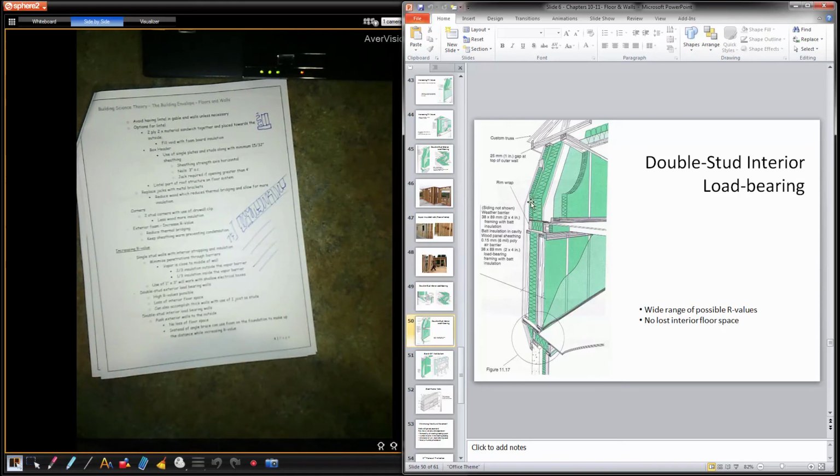But again, just overloading insulation. Insulation in between the sides, insulation in between the walls, then insulation in between the inner studs. Again, vapor barrier is on the back side of the interior wall, making sure that running wires and all those things are not becoming an issue. It also makes sure that, again, metal is not conducting the cold to come in.